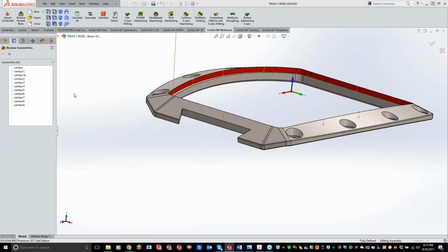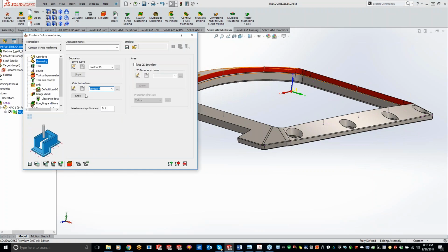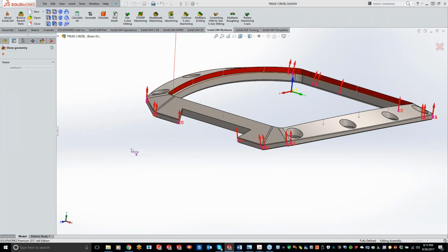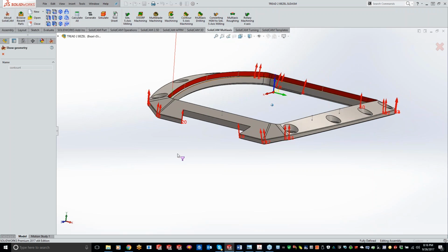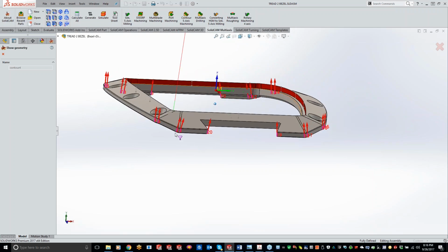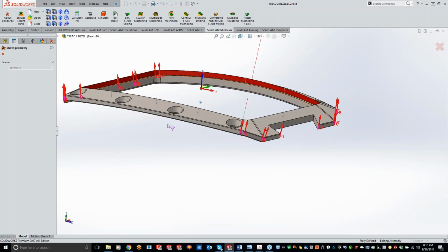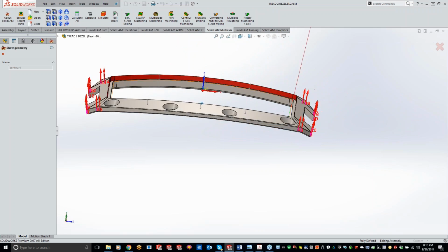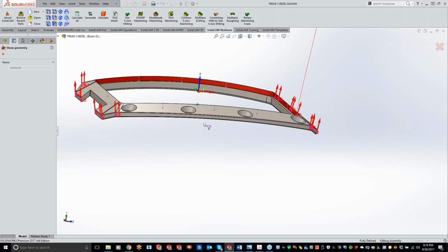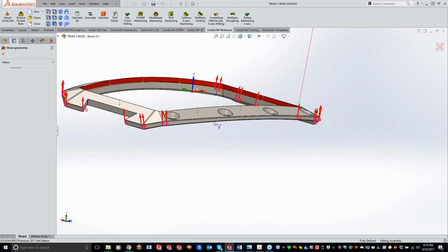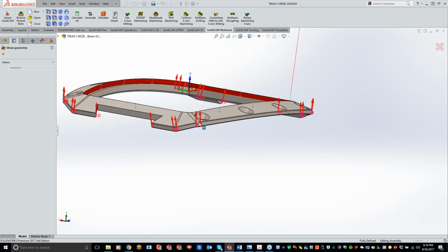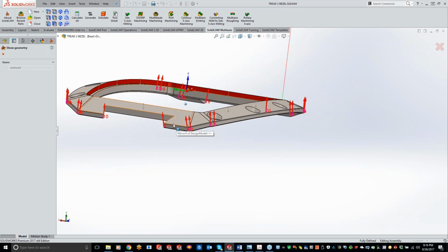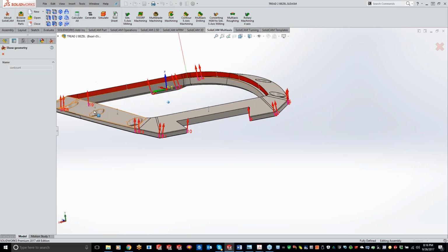And since I already grabbed those outside lines once, I'm not going to make you guys painfully go through that again here. So I have all my lines right here. And if I just do a show, we have all the lines pointing up. Like I said, I grabbed every single one. If I want to, I could add even more in here, or I could go less. It all depends on what angle you want that cutter to be at. Basically it's following the angle of these lines for that cutter going around.